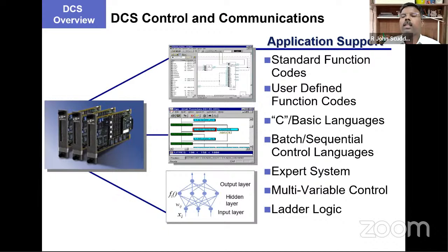So they are giving you certain important function blocks which are capable of handling so many normal situations. And in Nalco specifically, when we go into certain areas, we have also designed certain blocks which were not at all available in the DCS. We have designed certain new controls where we needed specific controls which the original equipment manufacturer of the DCS had not envisaged. So those things are also possible. But ideally, most of the standard function blocks are already tailor-made and available inside the DCS. It's a software platform.